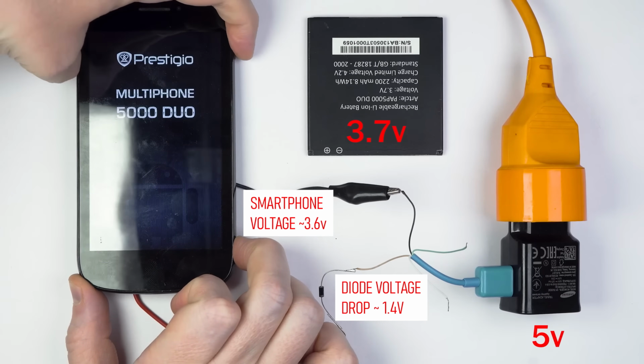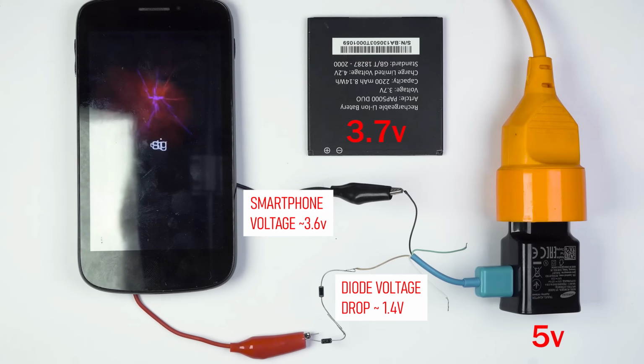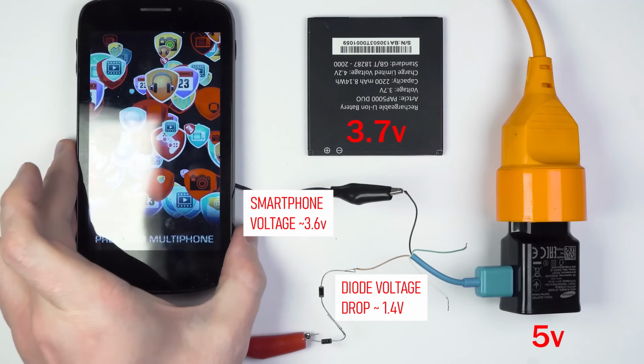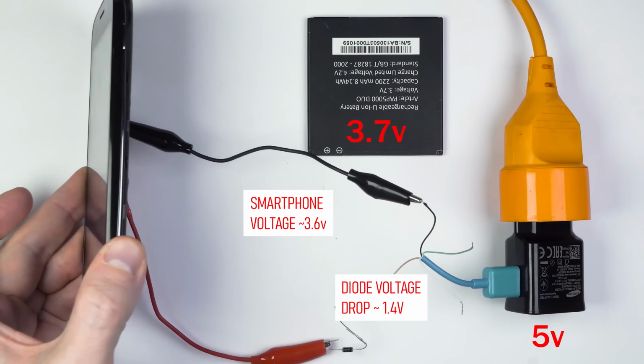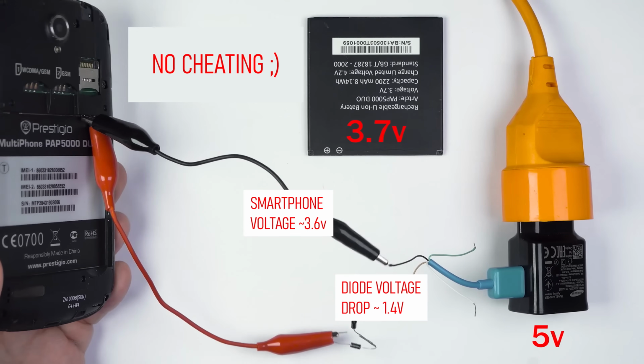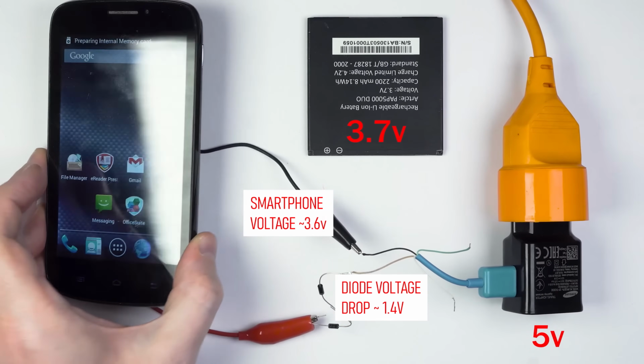which is basically what we need. And what's really important here is that, provided that the USB supply produces exactly 5 volts, the voltage at the output of our circuit will also remain stable, no matter what happens to the load, the phone. So, by wiring several diodes in series, it's possible, if necessary, to come up with a larger fixed voltage drop.